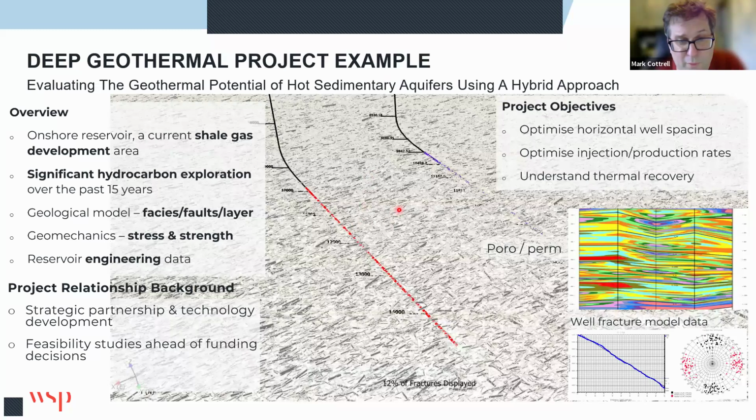That offset well, the well spacing for this formation, for these sets of conditions, is usually somewhere between 600 and 800 meters of separation. That separation is really key to understand. If we have the wells closer together, we can improve the likelihood of hydraulic connectivity between the two wells. So we can be more certain that fluid that we inject in one well is going to be produced hotter at the other well, but there are implications.